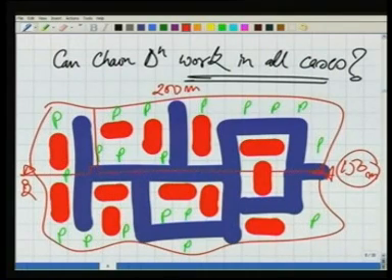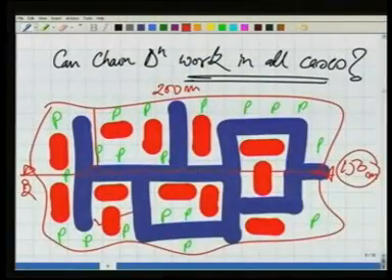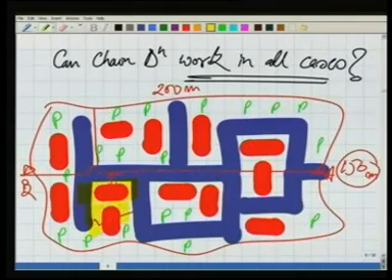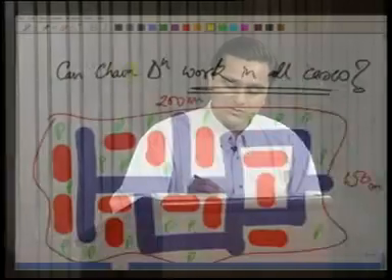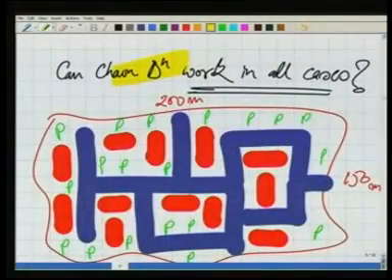Number two, another problem. If I need to measure an offset to this building, what will happen? This particular building is an obstruction here, because the buildings may be 1 story, 2 story. I am not supposed to climb over the building. So how to carry out the measurements? That's the problem. As we are talking about the chain triangulation, can we use chain triangulation then?